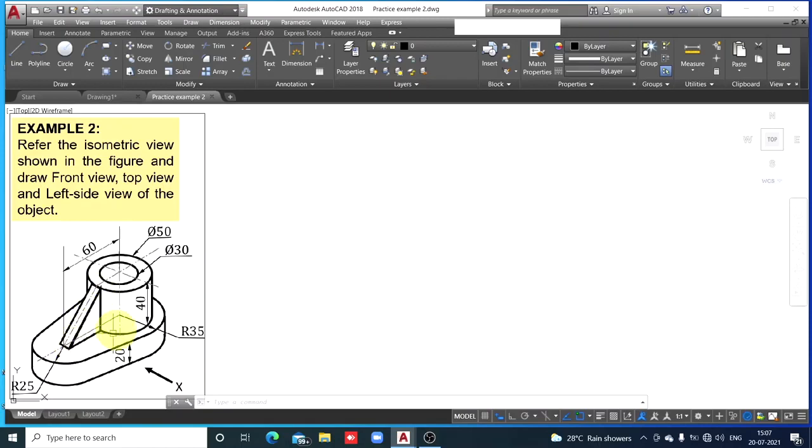In front view it appears a triangle and in the remaining two views, since it is a plate, a rectangle in the sense of a rectangular strip. And what is the thickness of this plate? Now thickness, watch here, it is to be measured parallel to this X arrow. Here it is thickness, you can see clearly, but dimensions are missing here. Thickness is nowhere mentioned. So we'll have to assume a certain thickness for this plate. Now compare this thickness with other given dimensions, and in proportion with the given dimensions you select the thickness.